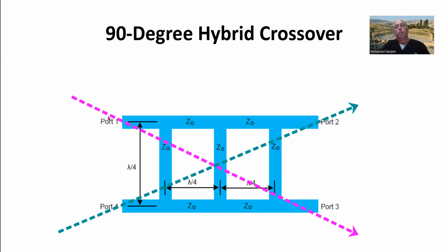But what we want to do, you could construct two 90-degree hybrids back to back, where the signal that comes in here actually gets out on this side completely, and it's isolated on this end, okay? And by doing this, you really implemented a jump over or a crossover, okay? Because the signal in here has to go past this one here, and in this case, this is all planar, so all in microstrip. If you can afford the landscape of this, sure, yeah, this is easy to do and works very good.